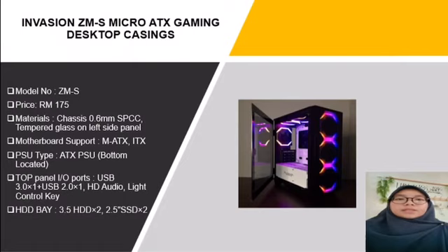The desktop case material is 0.6 mm SPCC chassis, with tempered glass on the left side panel. Multi-board support is MATX and ITX. The PSU type of this desktop case is ATX PSU, bottom located. The top panel I/O ports are USB 3.0 x1 plus USB 2.0 x1, HD audio, and a light control key. The HDD bay is 3.5 HDD x2 and 2.5 SSD x2.